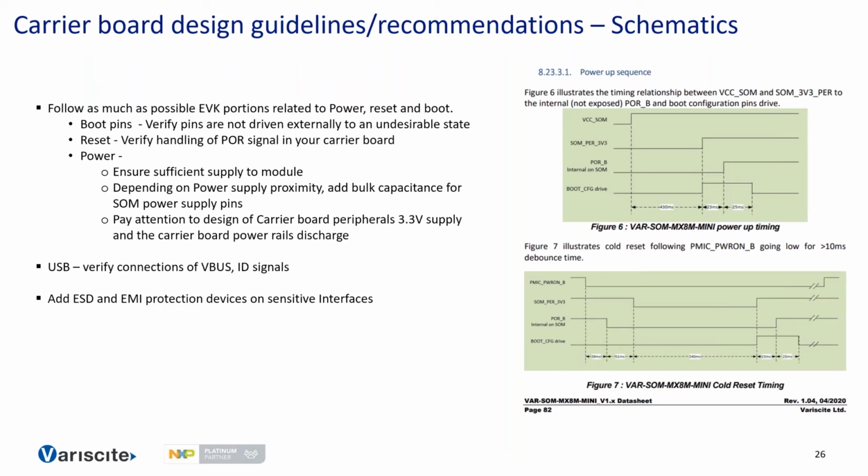Pay attention to the carrier board peripherals supply, and basically try to follow these areas as much as possible from the EVK, since they were validated on all of the SOMs of the family. So that will save you a lot of time.